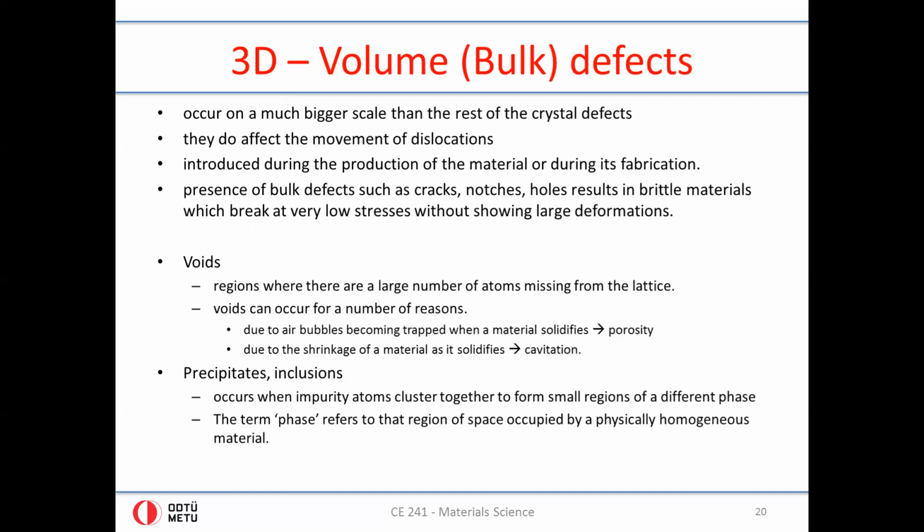And as a line of atoms are trying to move through the metal, when the turn comes to this line of atoms trying to move through this inclusion, this powder particle, it would not move. Either it wouldn't be able to move if it were a very strong material, or it would move with a different amount of difficulty, and it would cause changes in behavior.